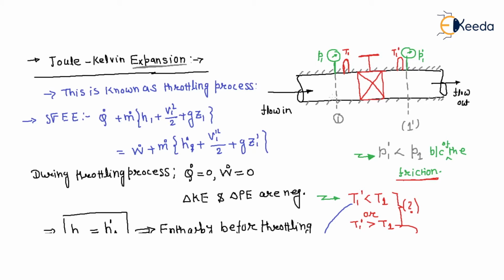Now if we close the valve gradually, right? First of all, you fix the state point at the inlet section. If you fix the pressure and temperature at the inlet cross section, then corresponding to that pressure and temperature, the enthalpy at section 1 is fixed, and with that fixed enthalpy you can flow the fluid into the control volume.